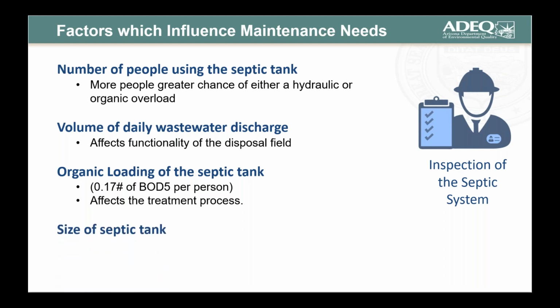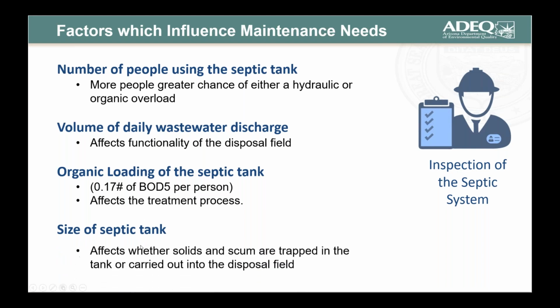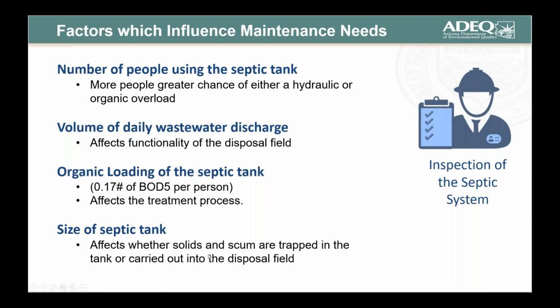And then the final factor is the size of the septic tank. And this is going to affect whether solids and scum are trapped in the tank or carried out into the disposal field. Now in Arizona, our requirement is 2.1 days of detention time in the septic tank.